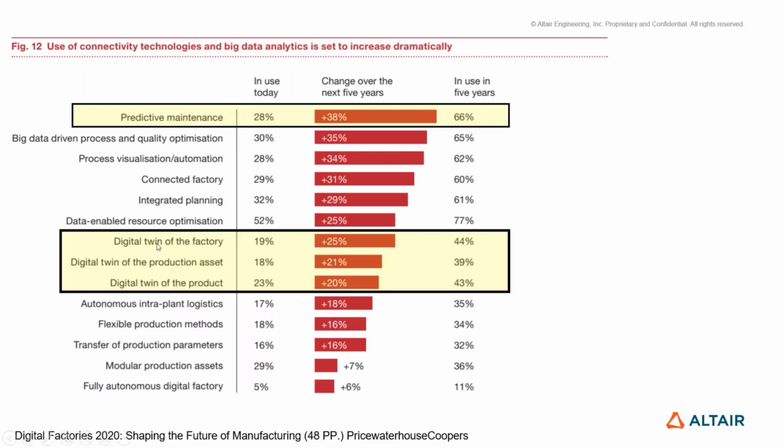There is a Raspberry Pi or a small chip inside, which gets data from the accelerometers or strain gauges fitted on your wheels, and it automatically runs a dynamic MBD model. In parallel it has some surrogate models, because the design is not changing, only the boundary conditions are changing. So it runs as a surrogate model, and in a few seconds it gives you the adjustment to be done on the shock absorber system.